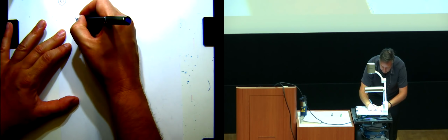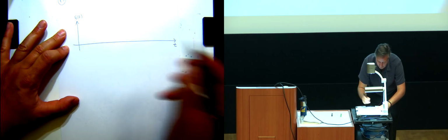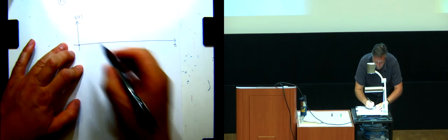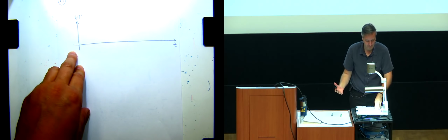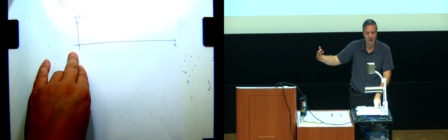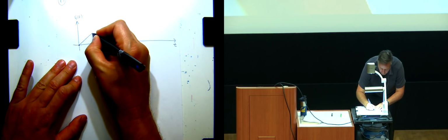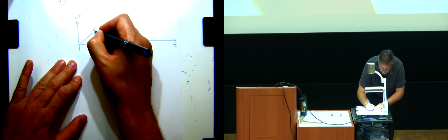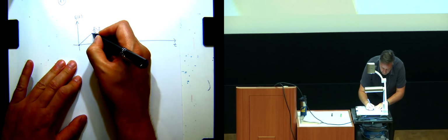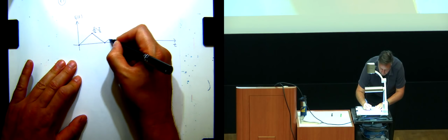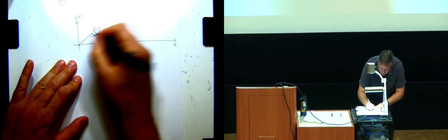So let's do this is Vc of t. And this is time. So let's say at 0 we start, and I'm just going to be drawing the Vc value. Assume there is some periodic current source that we applied, right? So it's going to go up to our I1 over C0 times T over 2. Going to come down, come back up, come down. These are the same values.